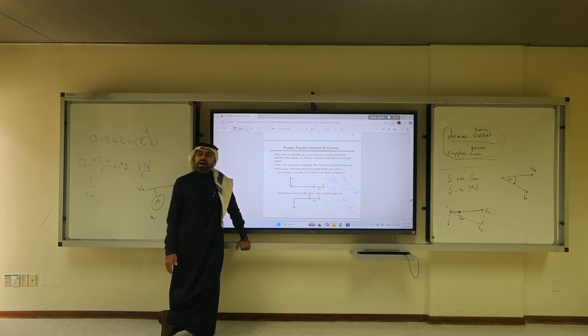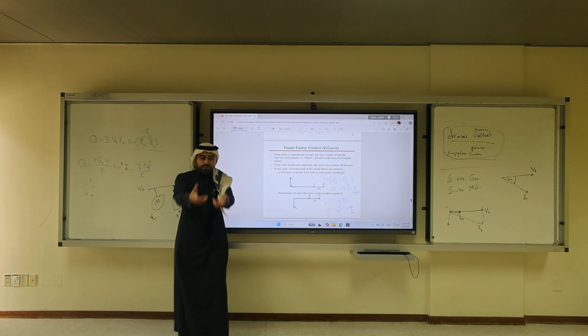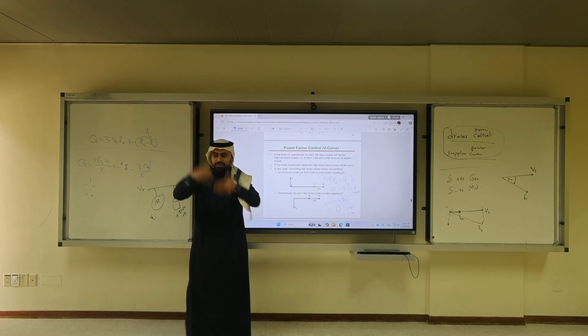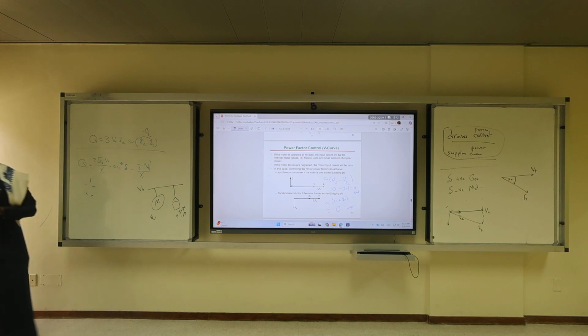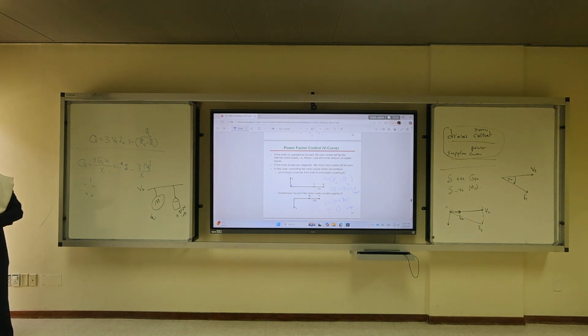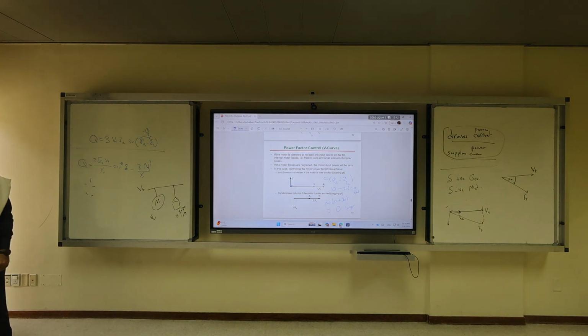You cannot have a permanent magnet synchronous condenser because you need field control. Now, if you physically change the magnets, if for some reason, Osama, I don't know, make this an idea, you want a synchronous motor with changeable magnets, that's an application for a synchronous condenser. Okay?